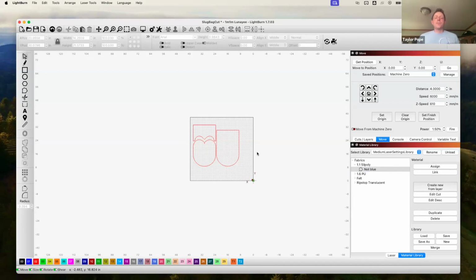The laser cutter is often an output device, kind of like a printer. The drivers, I think, are usually bundled together with a software. Lightburn, as I'm showing currently, is one of the more common ones. Laser Gerbil is a free one that's much less featured, but is still able to take vector graphics and send instructions to the machine.